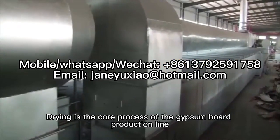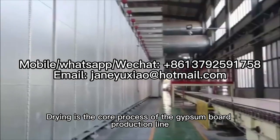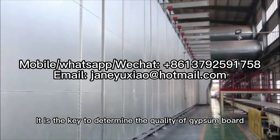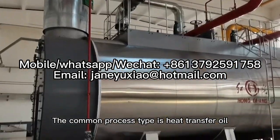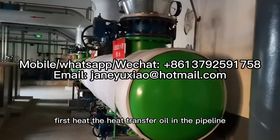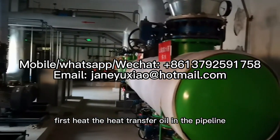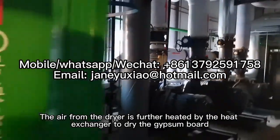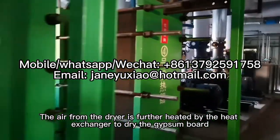Drying is the core process of the gypsum board production line. It is the key to determining the quality of gypsum board. The common process uses heat transfer oil. First, heat the heat transfer oil in the pipeline. The air from the dryer is further heated by the heat exchanger to dry the gypsum board.